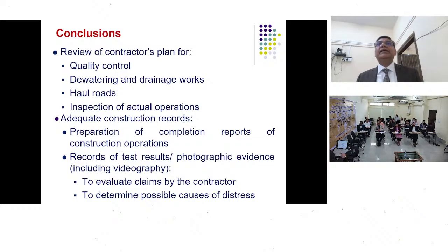Even after repeatedly telling them not to use the clay core as road, they use it as a road because if they use the shell material for transportation of their trucks, the tires get punctured, so they start using the core. Even though as per standard practice, they should use some steel plates to cross the clay core, and they should have layers of steel plates or some other material on the shell material to move on.